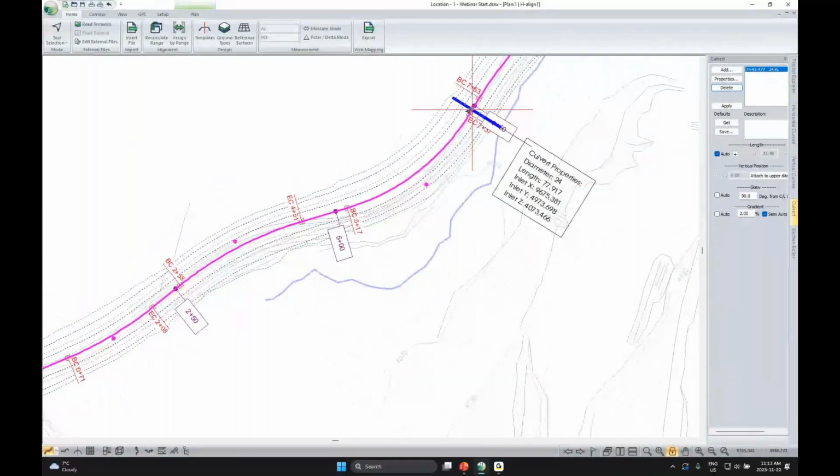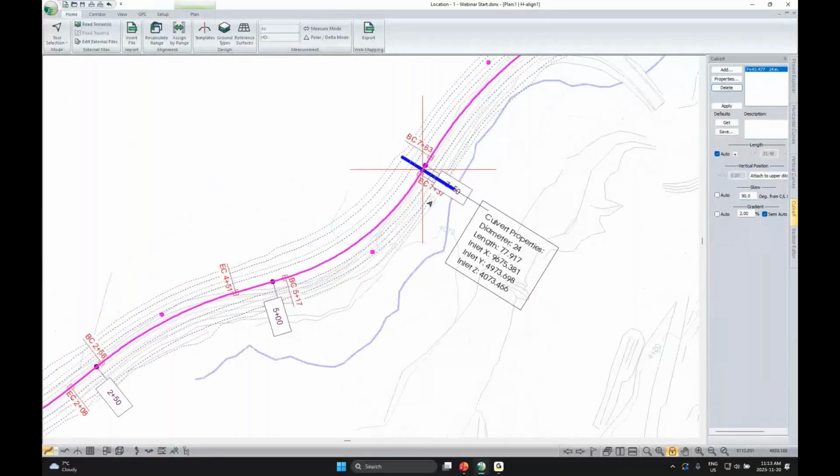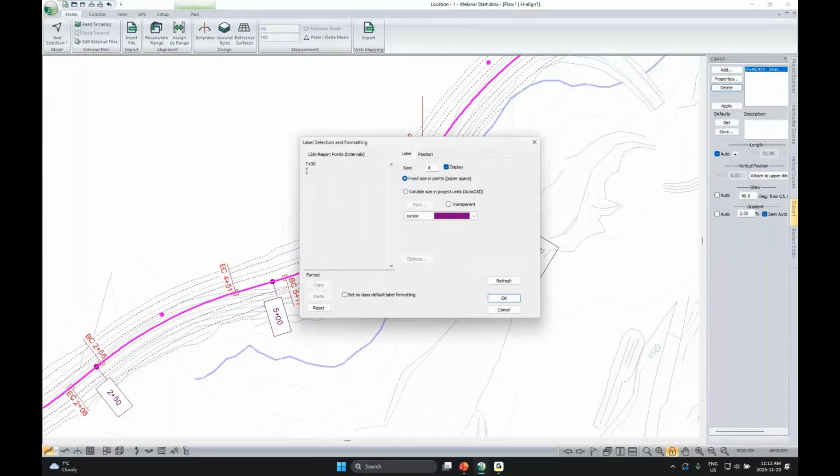And then we get to singular labels, where I'm actually quite happy with my station labeling. But in this one particular instance, it's definitely a bit of a mess and it's not very clear. We've got overlapping begin curve, end curve labels. We've got a leader coming through our station label, and we have the ability to manually edit individual labels. So to get there, and maybe I'll just do that again, I right-click and select Edit Label Tool. I click once on the label to turn it into manual edit mode, and then I can double click it and change any of the properties for this individual label.